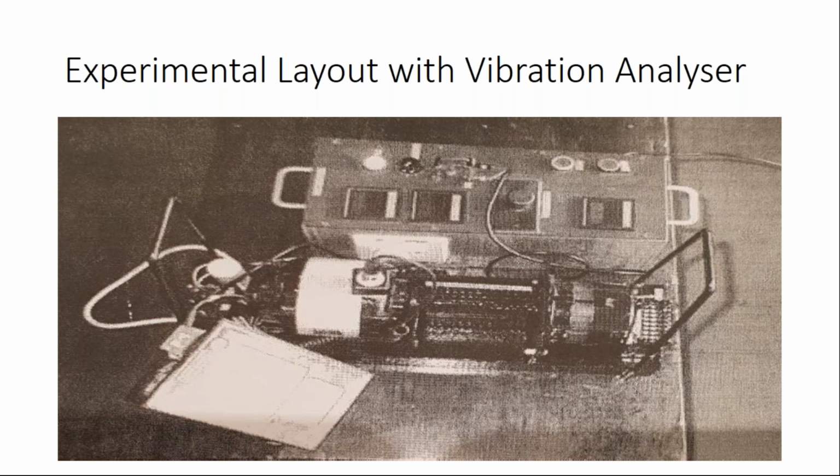This photo is basically the setup. So you have a single phase machine, a single phase capacitor start motor, connected via a shaft coupling to the alternator, which is basically the car alternator. And this little box is the switch box. And here you measure the voltage and the current, etc. for each of the machines. And also you have a little rheostat, so you can vary the excitation on the alternator. And in that way, you vary the load on the motor.